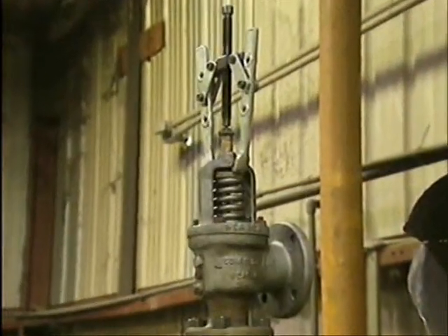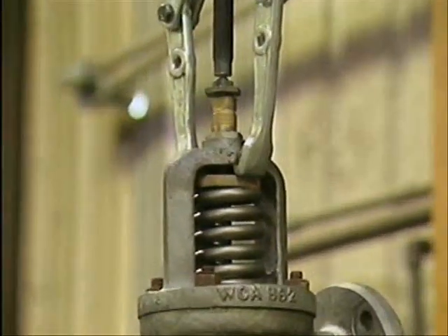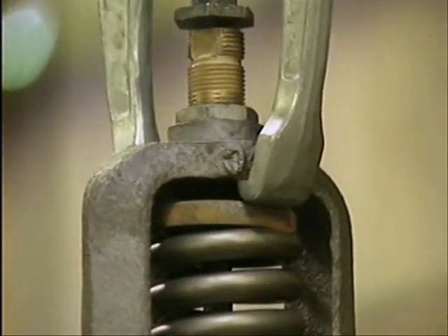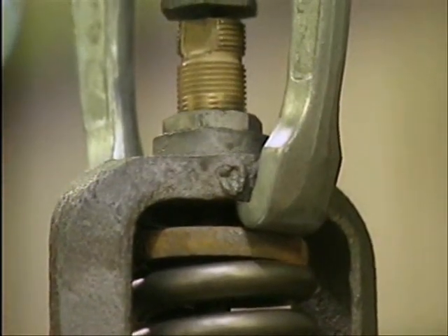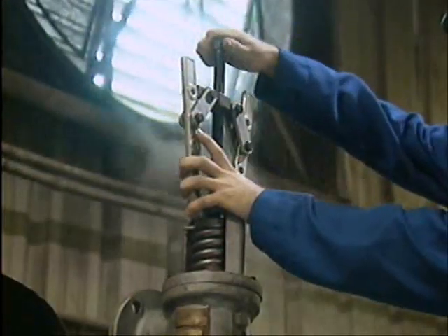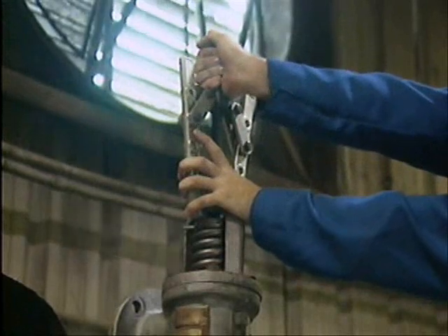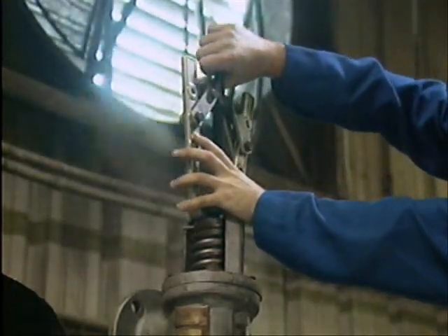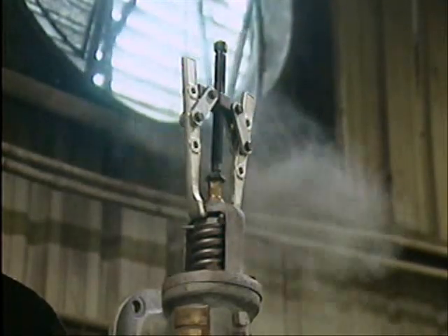If the gag on a safety valve is properly aligned and tightened, the valve won't leak during hydrostatic testing. But if the gag isn't installed properly, the valve will lift slightly during the test and sizzle. If this occurs, you should reduce system pressure until the valve closes. Then you should adjust the installation of the gag. Trying to pinch off leakage by tightening the gag without lowering the pressure could damage valve parts.